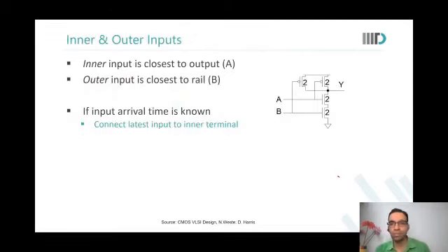So what exactly did we discuss? I was not able to get what Ranjit was mentioning. So Ranjit was mentioning that if it's a complex gate, it matters still more. Suppose A and B are in parallel and C is in series in the NMOS stack. If transistor C is connected to the output and A or B are in parallel connected to ground, then there would be one delay.